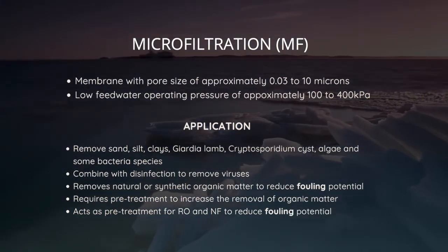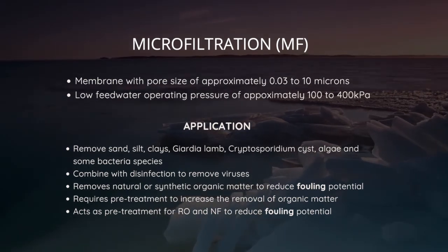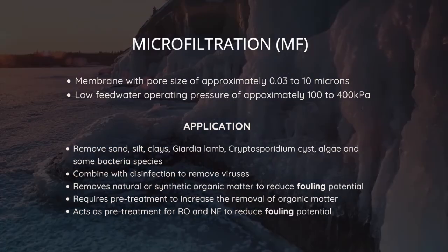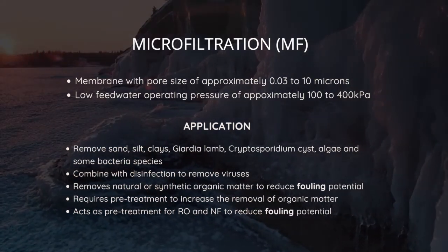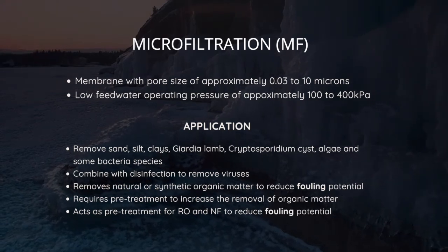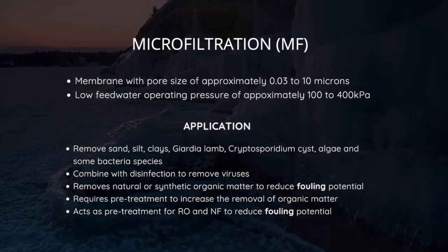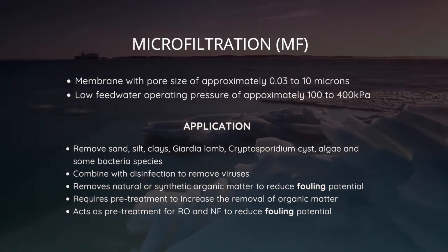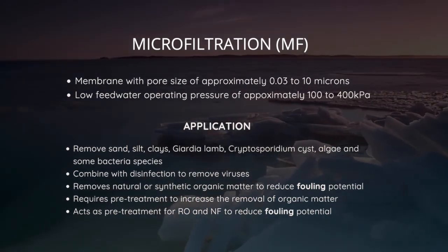Microfiltration also removes natural or synthetic organic matter to reduce fouling potential. It also requires pre-treatment to increase the removal of organic matter. Microfiltration can also act as pre-treatment for reverse osmosis and nanofiltration to reduce fouling potential.